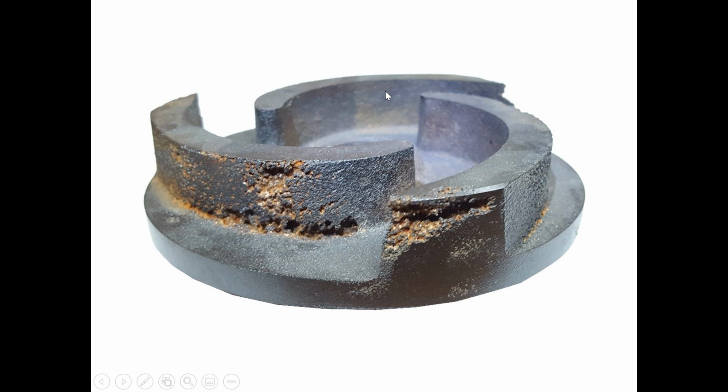And what happened in this dam in Russia is that they had really fast-moving water that was cavitating, and over decades there was enough of this pitting and erosion of the impeller that it became a little bit imbalanced, and it was vibrating because there was more metal loss on one of the impellers than on the other. So this spinning turbine is connected to a spinning impeller, and it was vibrating a little bit.